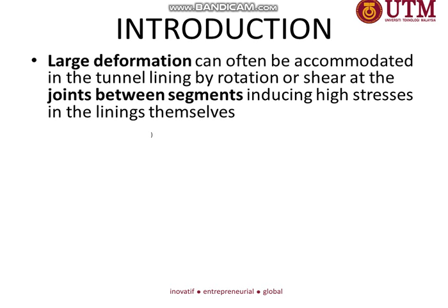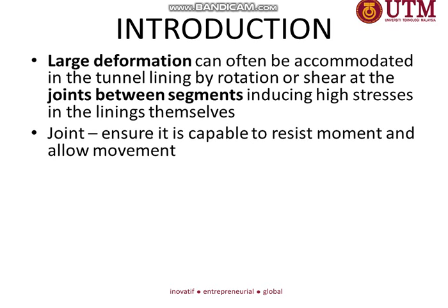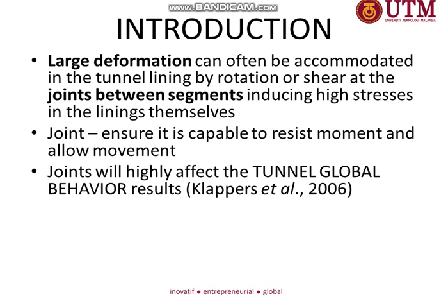Large deformation can often be accommodated by the tunnel lining, either by rotation or shear. This will induce high stress. So tunnel lining design is an interactive problem, because we want to allow the movement, but we want to reduce the stress or bending moment. The joint is there to ensure the tunnel is capable of resisting movement and at the same time allowing movement.